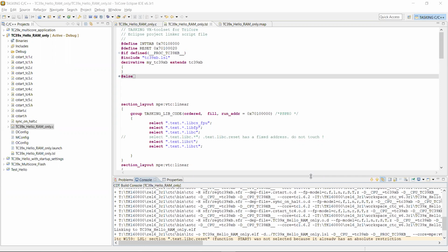So if you choose to have, for instance, calibration data or something like that, that you also want to store in an EEPROM, but where you want to keep a copy, which is corruption protected, for your calibration of your application, and you absolutely want to know that it's not being corrupted, then you store it in the LMU RAM and you enable the ECC protection.